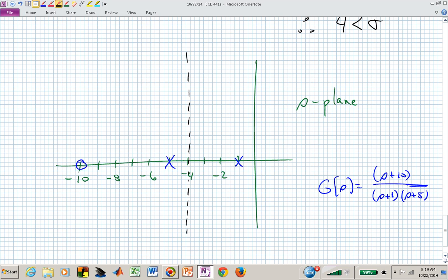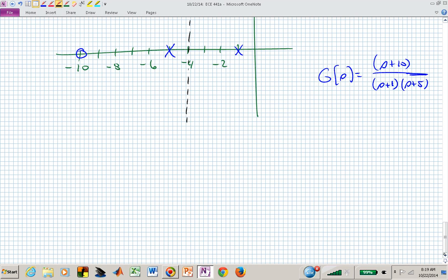That corresponds to an e to the -t. The pole at -5 corresponds to an e to the -5t. E to the -1t is much slower than e to the -5t. This pole at -1 dominates your response. Let's just see that. Suppose somebody says, well, maybe I don't have to do much. Maybe I just apply a constant input to the open loop system, and I will satisfy my settling time spec. We sort of know that that's not going to be true based on our sketch just now.